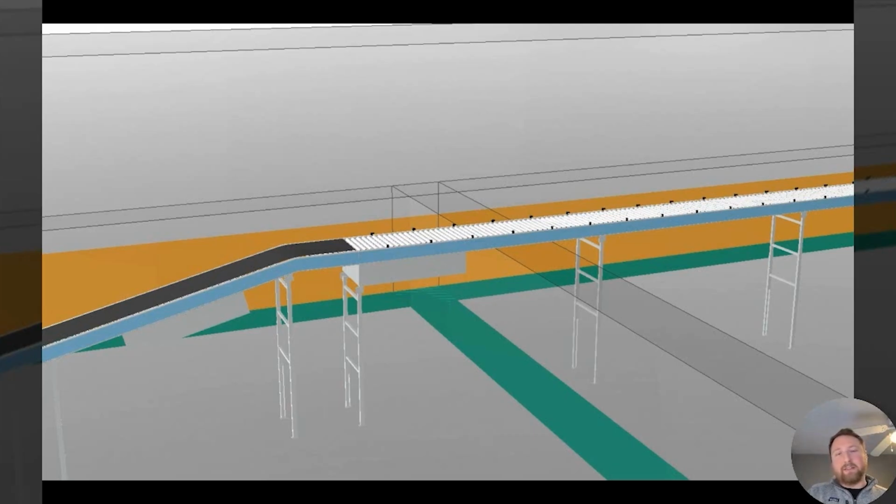And then use those different paths both in 2D and in 3D, to the point where you don't need to, early on in the solution development process, do a 2D elevation to show that we have walk clearance under this conveyor. If you have the block, say that it's the 2.1 meters that you need to walk under, and move on. You can color code those too, so that across the building everyone understands that these are my pedestrian paths, these are my industrial truck paths, and that's really clear and communicative.